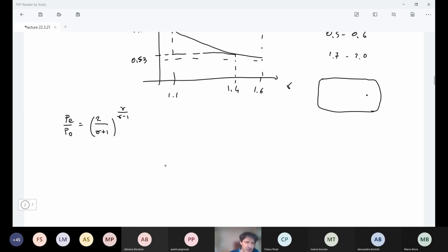And we have that ṁ is equal to P0 AE square root of 2 gamma over gamma minus 1 over RT0. And then here I have to replace this, it was to the power 2 over gamma, and it becomes now 2 over gamma plus 1. That here was 2 over gamma, becomes 2 over gamma minus 1, because of this gamma here.